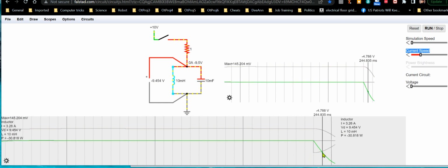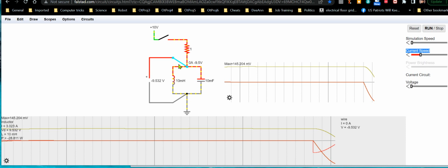It goes back and forth. It oscillates. But anyway, as you see, the current decreases, well, the voltage you're seeing is actually the voltage across the capacitor, which right now is approaching negative 10 volts. Because that inductor, if you recall, at first had 0 volts across it, but the moment we disconnected that source, the voltage flipped from what it used to be. It used to be a plus here and a minus here, but now you can see it's a minus here and a plus here. The inductor's voltage flipped